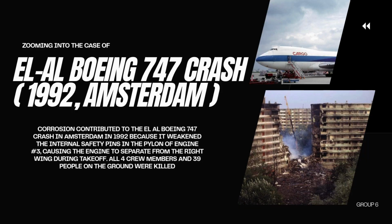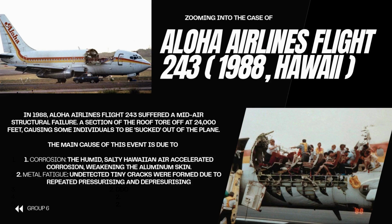Now, let's zoom into some examples. In 1992, an El Al Boeing 747 crashed in Amsterdam after an engine broke off due to metal fatigue. The detached engine damaged the wing and control systems, causing the plane to lose control. In 1988, Aloha Airlines Flight 243 lost parts of its fuselage mid-air due to metal fatigue and corrosion. Years of repeated pressurization caused tiny cracks to grow, while Hawaii's salty, humid air sped up corrosion, eventually leading to the dramatic structural failure. These examples highlight the importance of picking the right material for the right vehicle.